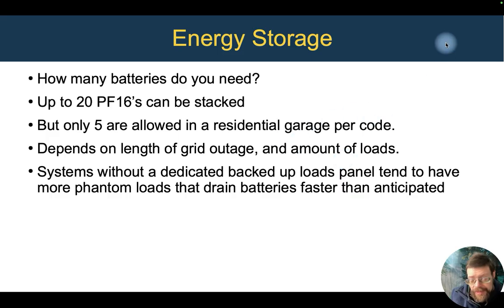Looking at energy storage, how many batteries do we need? Really depends on how long of a power outage and how much power we're using, how much energy we need. Up to 20 of the PowerFlow 16s or 20 PowerFlow 5s can be stacked. So if using the PowerFlow 5s, that's 100 kilowatt hours. If using the PowerFlow 16s, that's 320 kilowatt hours.